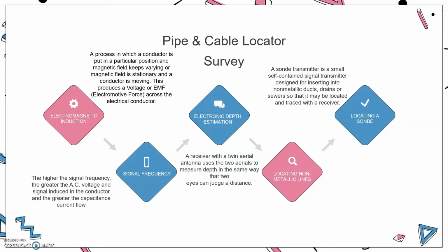For a current to pass, an electric circuit must be completed. The detectability of current flow in a properly insulated buried conductor is influenced by the low-powered signal source at the surface. The available voltages are unable to pass through insulation, and capacitance in AC circuits also has an effect on current flow detectability.